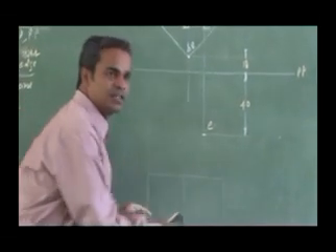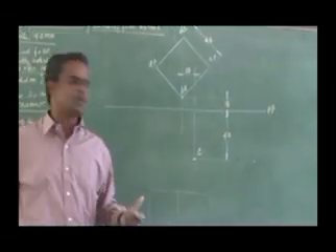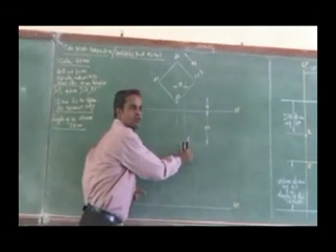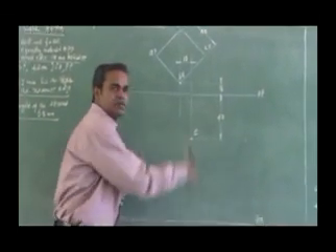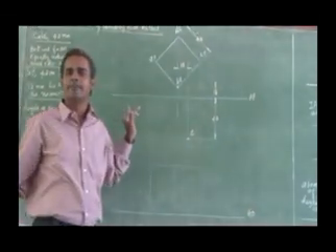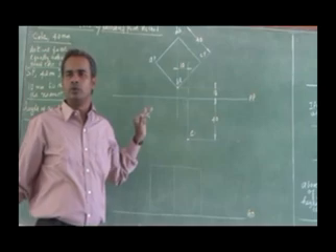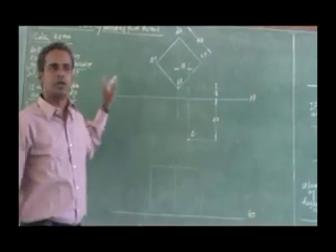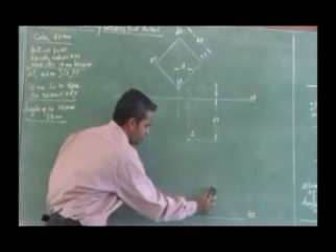So I just have to mark the corners. Then as usual, with the previous procedure, the station point, top view and front view will be there. You have to connect everything to the front view. As in the previous method, I can go for the perspective view. Now it is 2-point perspective. I am trying to show the perspective view.